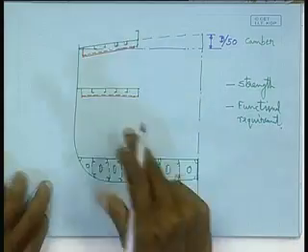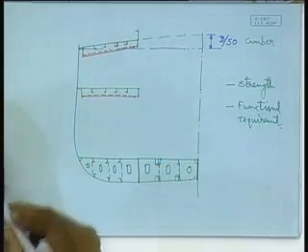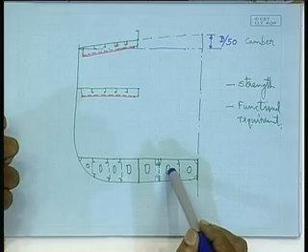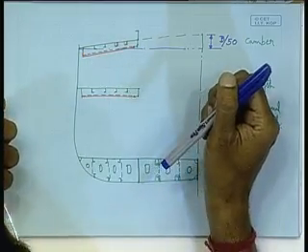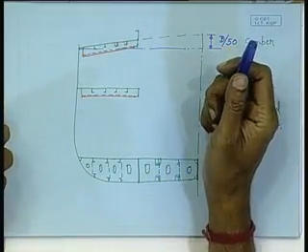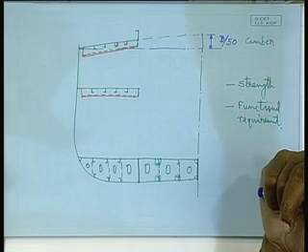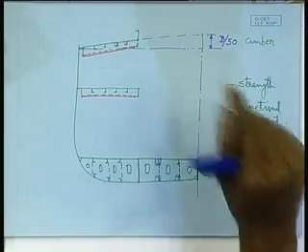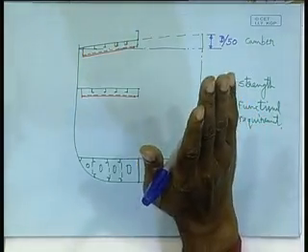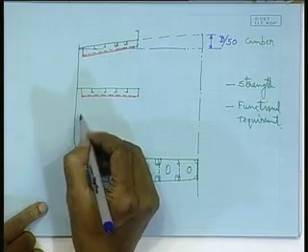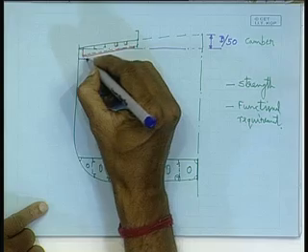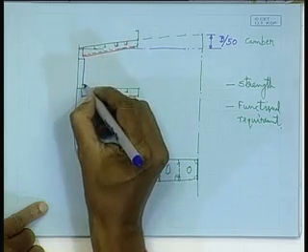So that logical requirement tells me that the double bottom should be longitudinally stiffened, and the decks should be longitudinally stiffened, because we know a longitudinal stiffening arrangement provides a better buckling strength, thereby I attain a better strength to weight ratio. So that is a better way of doing things. In the same logic, my side shell also can be longitudinally stiffened, but here we will not do longitudinal, we will do transverse framing, transverse stiffening, right.